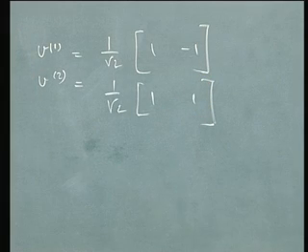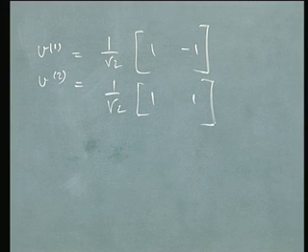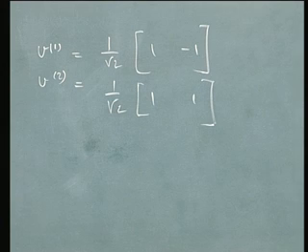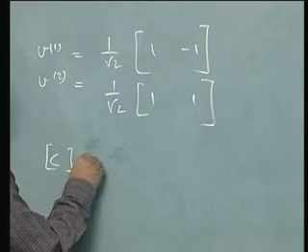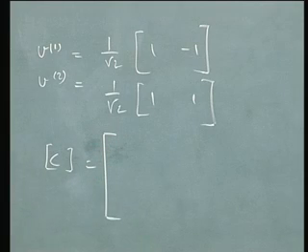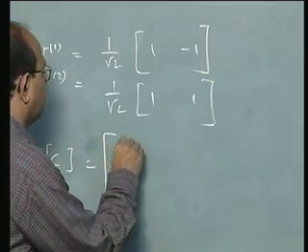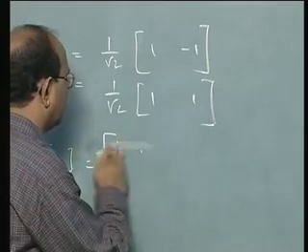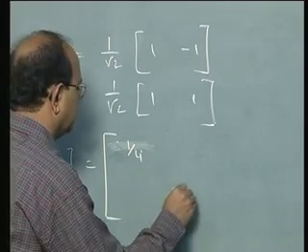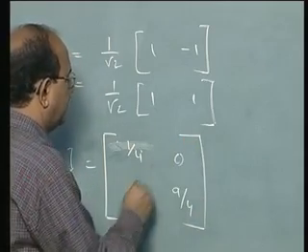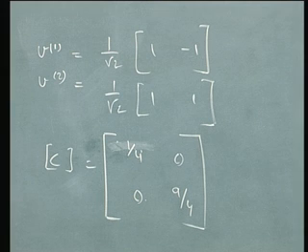So look at these steps, this is how you calculate stretches, because these kind of calculations may become very important when you implement finite element analysis later. So in other words, how do I write the C matrix? This is spectral decomposition, in terms of these lambdas, written as 0.25 or 1 by 4, and 9 by 4, right?